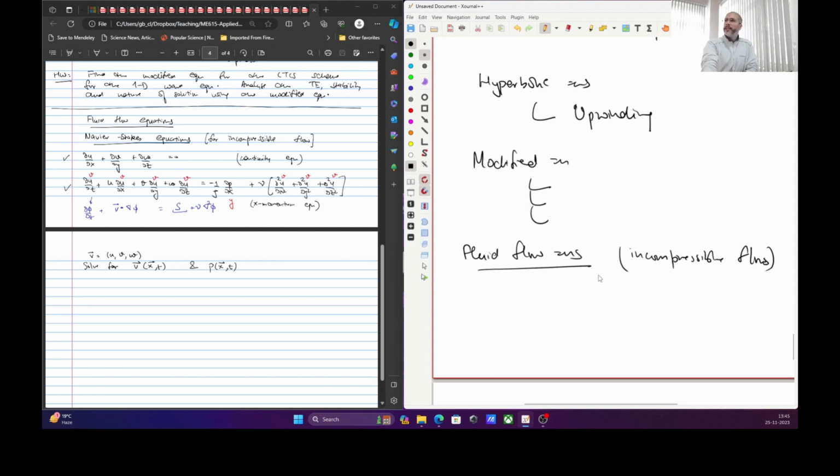And why is that? Why is solving incompressible flow equations difficult? Because not density but pressure. So pressure, there is no explicit equation for pressure, but pressure appears in your velocity equations. So indirectly, the pressure equation is derived through the continuity equation, right?